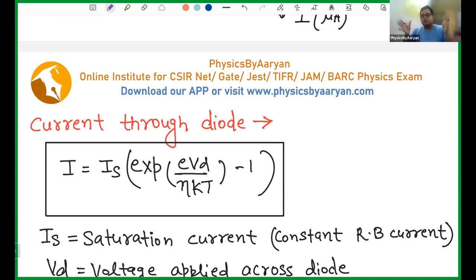Within this 10 ampere, we can use our Zener diode. So every Zener diode will come with the rating that you can give it a maximum current of this. You cannot give it more than this current. Otherwise, its own voltage will change. So we can change, but there is a limit to that. Within this limit, it will not change.